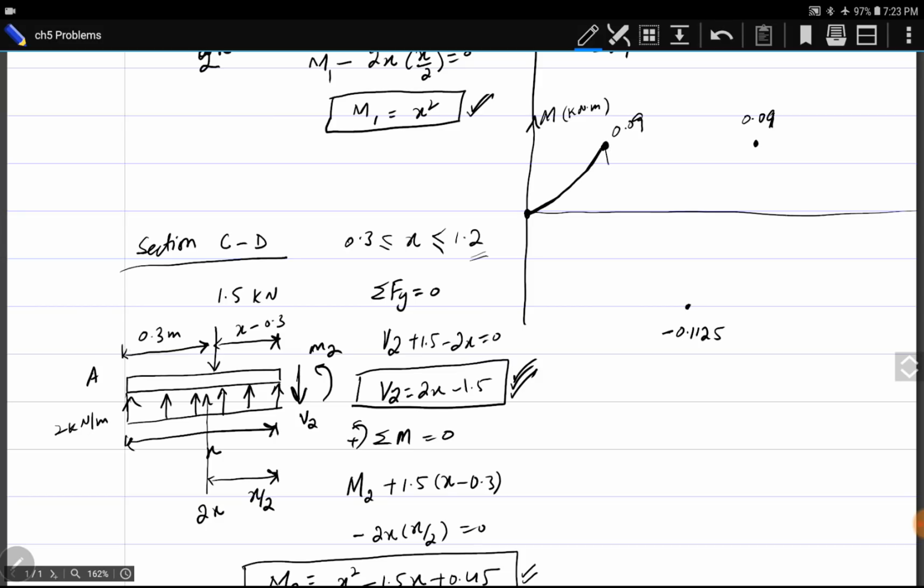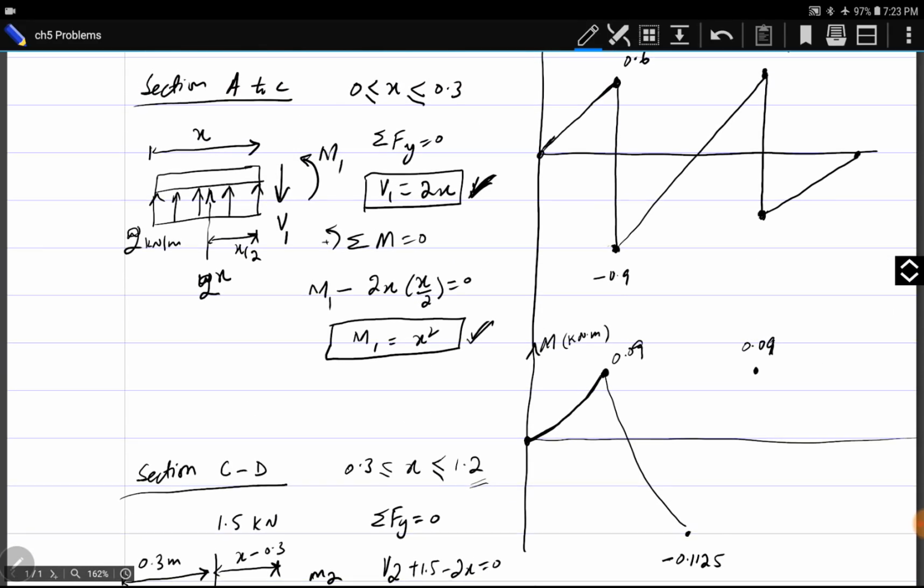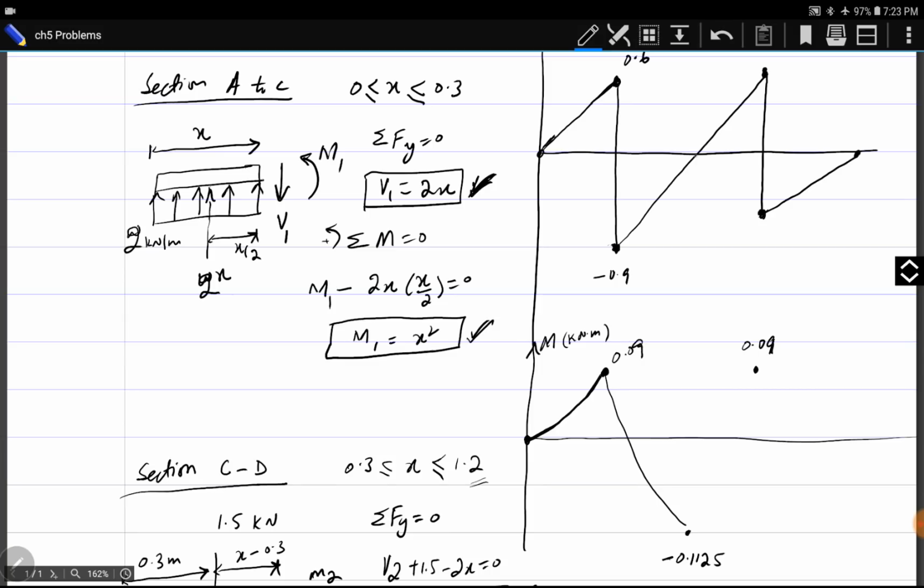So it means here it is a curve. Okay, how we will draw the curve? If you see here, between these 2 points, the slope of the shear force is increasing. So I will draw a counterclockwise curve here. And then again, slope between these 2 points is again still increasing. So here another counterclockwise curve will be drawn.